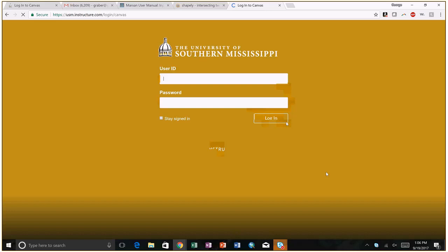Another reason is this PDOP error. Most drones contain fail-safes. They won't even let you take off if the PDOP is too high because it knows that location could be off by a lot. You could crash into a building or something.